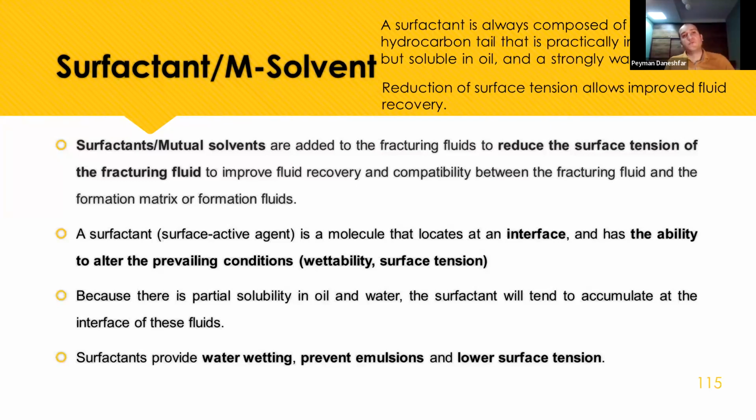They reduce the surface tension of the fracturing fluid to improve fluid recovery and compatibility between the fracture fluid and the formation matrix and formation fluids. The surfactant is a molecule that locates at the interface and has the ability to alter the prevailing conditions such as wettability or surface tension. Surfactants provide water wetting, prevent emulsion, and lower surface tension.